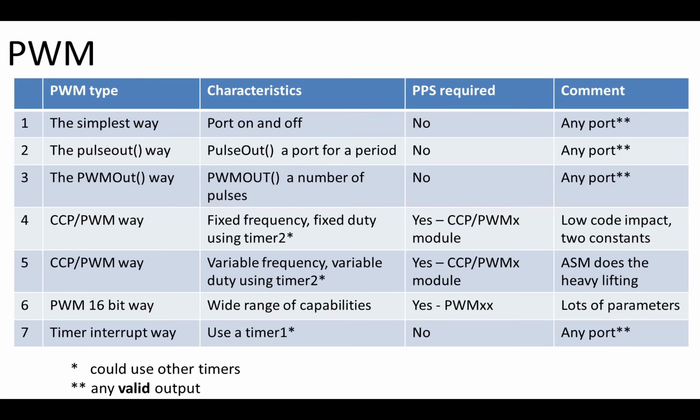6th way, PWM 16-bit. Wide range of capabilities, fantastic, 16-bit pulse width modulation. Yep, you're going to need the PPS, but you're going to use a different module. It's called the PWM module, and there are lots of parameters or registers to be set up.